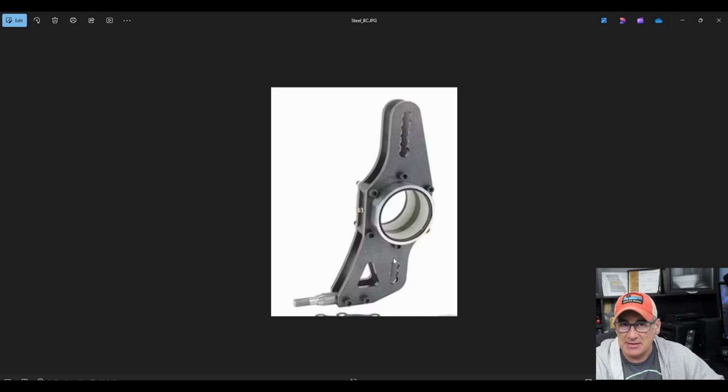Now we refer to it as a decoupled suspension because these bird cages, or the brackets where the 4-bar links connect to the axle housing, are not rigidly mounted. If you think of a traditional car, like a 4-bar metric link suspension on a street stock or something, the brackets where the connecting links connect to the rear end are solidly welded to the housing of that axle. So when we apply power to a live axle, the axle is going to have a tendency to counter rotate with the power that's coming through the engine.